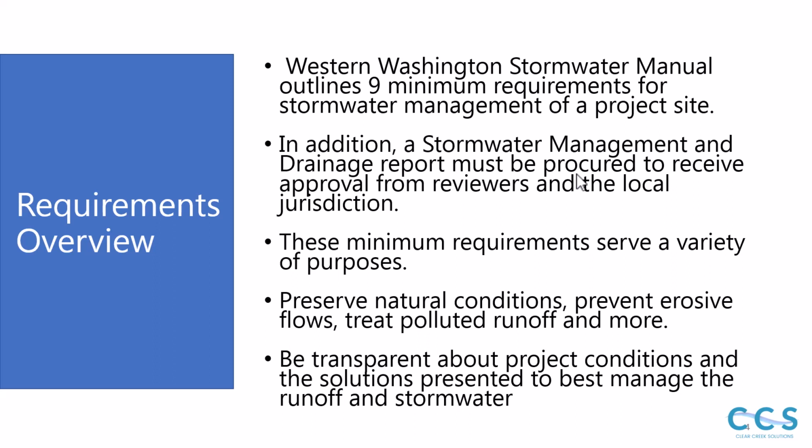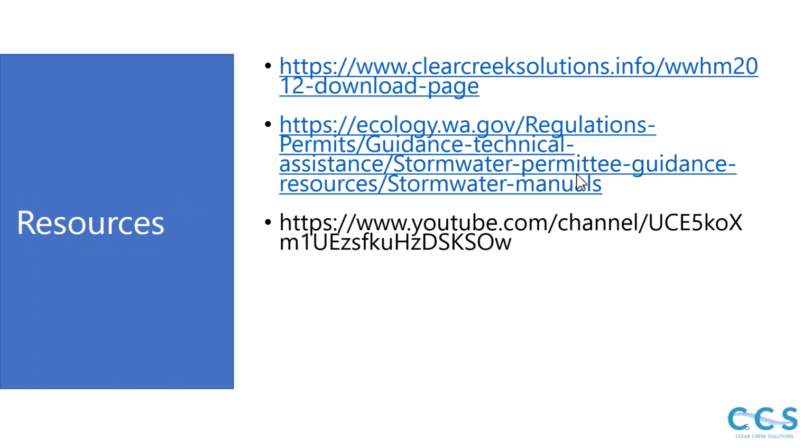Let's make sure that we aren't reckless with our designs, that we are using natural processes whenever possible to preserve the pre-developed conditions of your project site. They help to preserve natural conditions, prevent erosive flows, and treat polluted runoff, among many other things. There are also some restrictions for when we're actually constructing the site, such as having an erosion control plan. It's just encouraging engineers to be transparent about their project conditions and the solutions presented to best manage the runoff and stormwater from your project site.